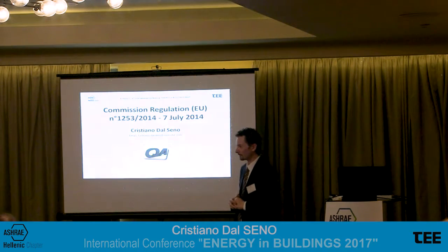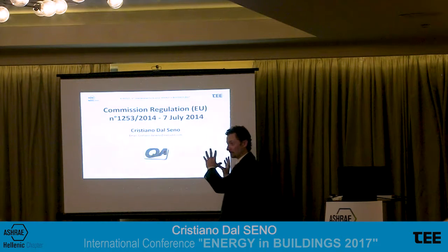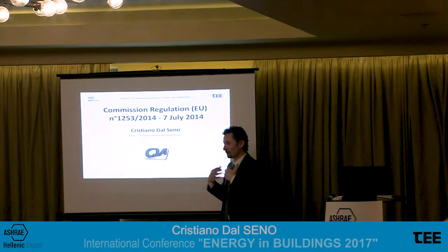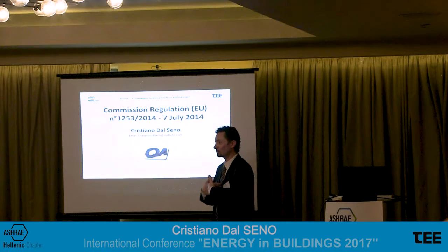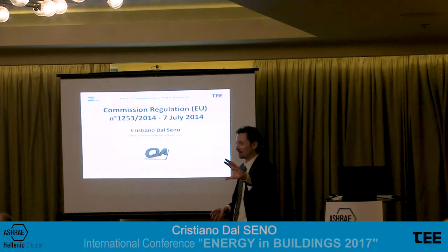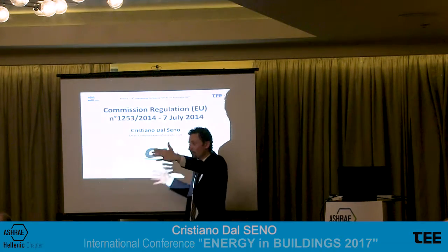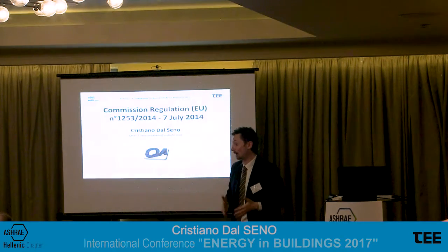Can I ask you about the water pressure drop on the coils? Yeah. And how does it affect the energy consumption of the unit? This is one point that integrates your observation. It seems from the regulation that I, as a producer, stop my calculation at the manifold of the coil, and then I forget what is outside. So I can do the best performance in my air handling unit, and then with a small air handling unit like this, you have a pump big like this because my pressure drops are too high.